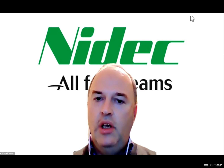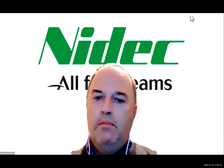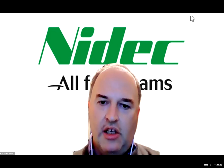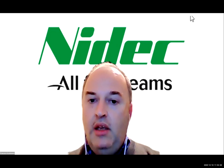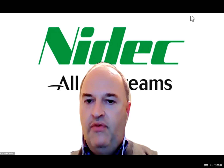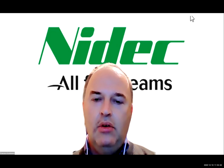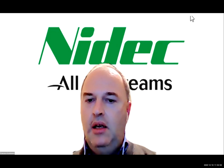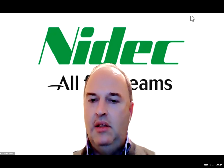So this is a system that is more material friendly. It helps you to keep the material tension under control, because it's not pushing hard to the maximum. Anyway, it doesn't matter what kind of expeller you have. When you set up a loop control, it is important to find out for each loop former the sweet spot, the height sweet spot, because depending on the material size and on the size of the loop former, you achieve a better result when the loop is running at a certain height. And that certain height is where you don't have tension in the material.